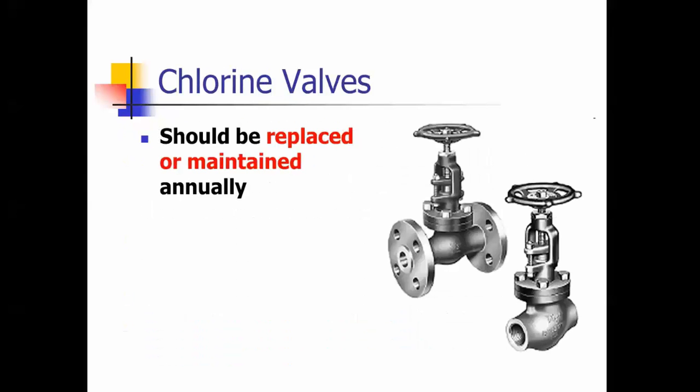Chlorine valves should be replaced or maintained annually. You might see this on the test. So you want to have those looked at. We had a valve company look at ours periodically, annually.